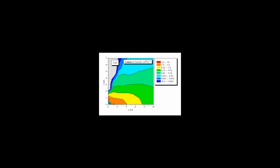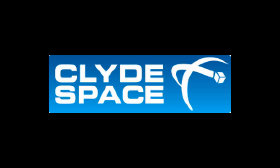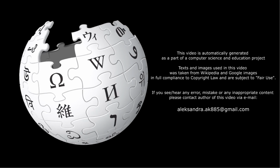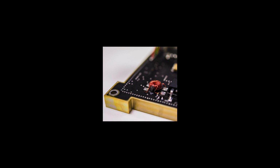The pulsing occurs due to the time needed to recharge the plates following each burst of fuel, and the time between each arc. The frequency of pulsing is normally very high and so it generates an almost continuous and smooth thrust. While the thrust is very low, a PPT can operate continuously for extended periods of time, yielding a large final speed. The energy used in each pulse is stored in a capacitor. By varying the time between each capacitor discharge, the thrust and power draw of the PPT can be varied, allowing versatile use of the system.